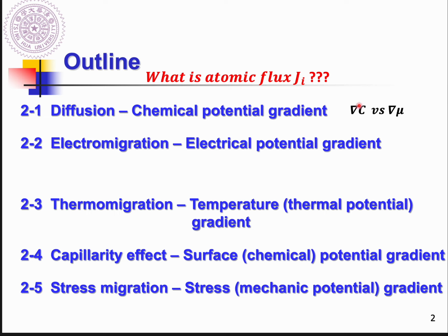But as I mentioned in previous lectures, spinodal decomposition is a very typical case to demonstrate that instead of the concentration gradient, the chemical potential gradient is exactly the real driving force for diffusion, because in spinodal decomposition, atoms move from the low concentration site toward the high concentration site. So we know that the driving force for diffusion in solid materials is the chemical potential gradient.